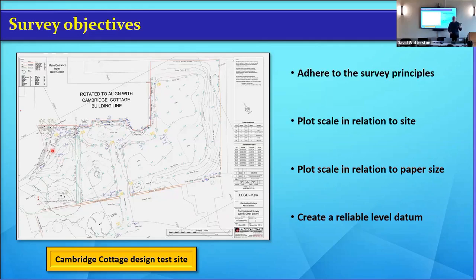It gets confusing. But the survey equipment that's used today, the total stations, the scanners, the drones, generally works to very similar accuracies. They're down to millimeters, and certainly to angles of arc. But the drone's not going to use angle of arc, neither is a GPS, it's only surveyors. So it's all pretty much a muchness. If I surveyed that wall out there with my instrument, which is 1 second of arc, 1 millimeter in distance, I'm going to fix the points to whatever they are. Now I can reproduce that at any scale you want.